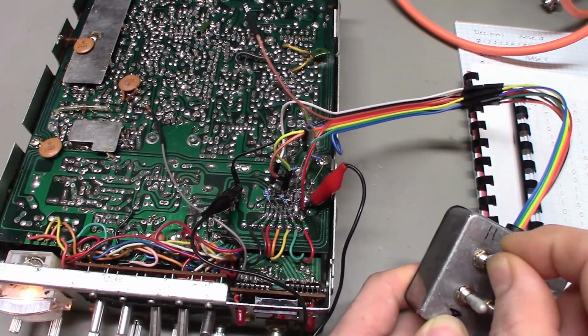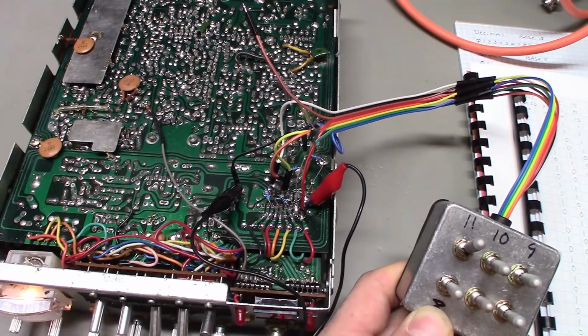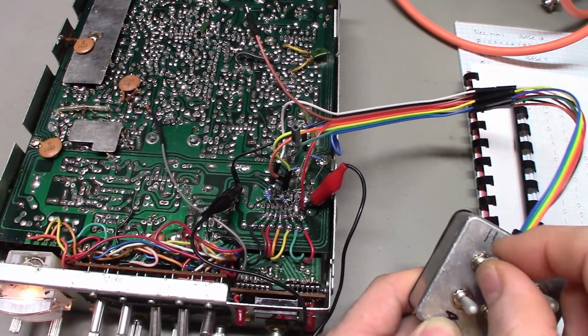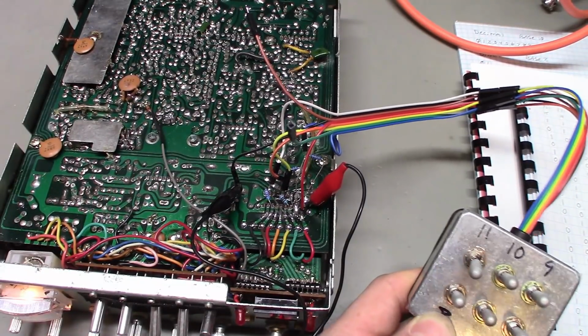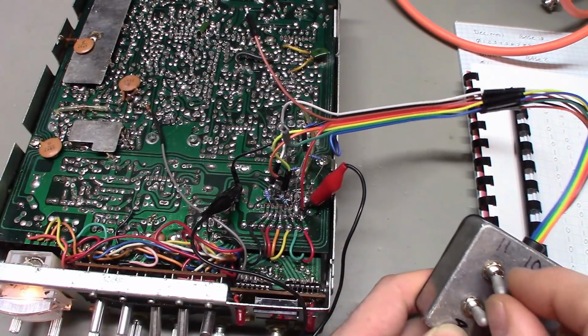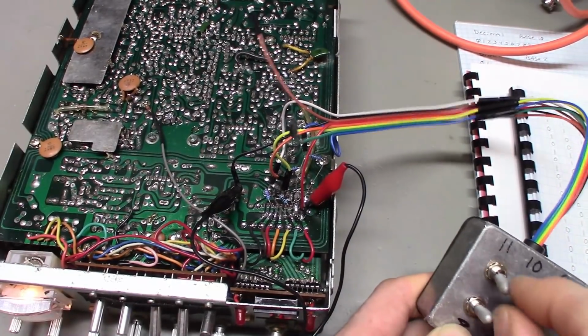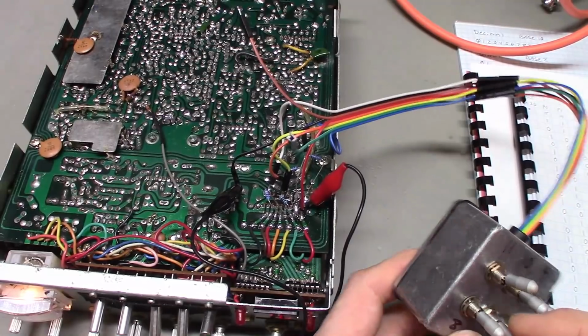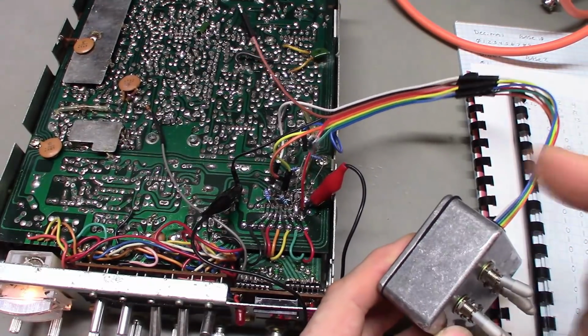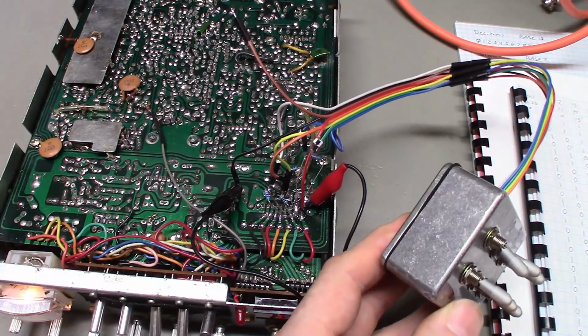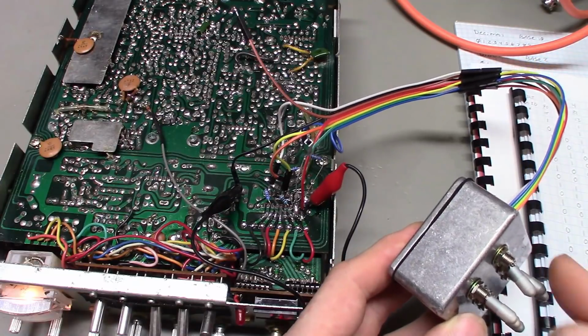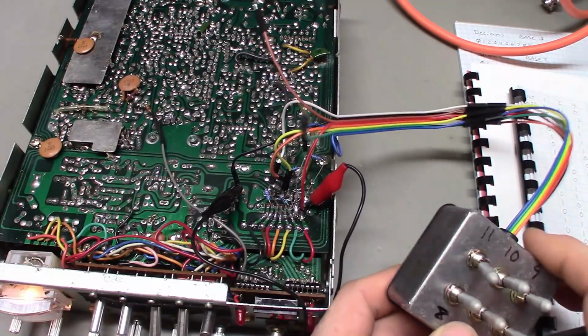They're not attached to the positive or to the negative. When I flip the switch up, that's a logic level high. It kind of makes sense, up high and down low. That's the way I look at it. So that's a 0, that's a 1, okay? Switch is up, it's in the high state, it's supplying a voltage. When I put the switch down, it's a 0, a low, it's applying a ground to the pin.